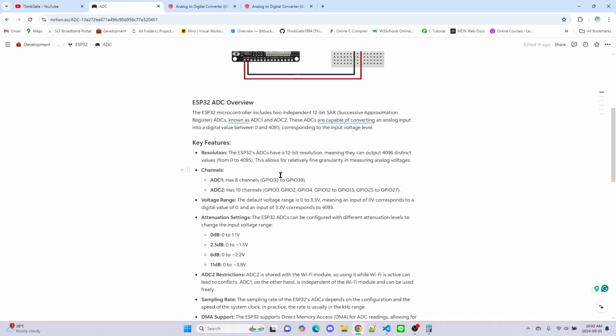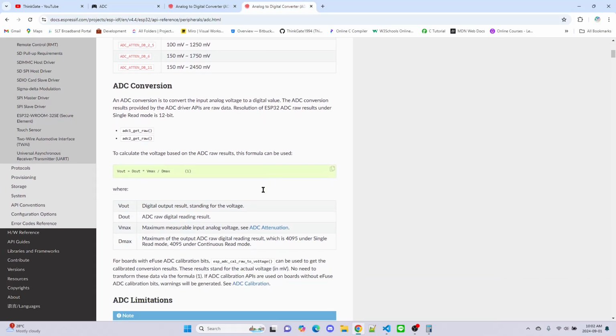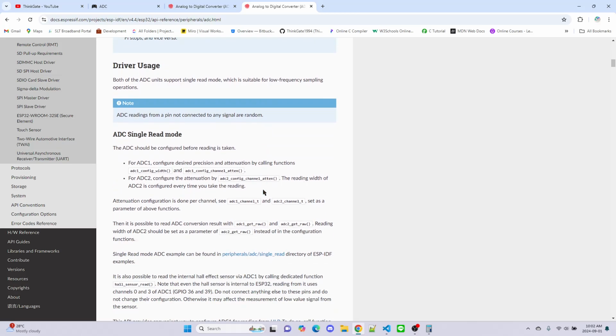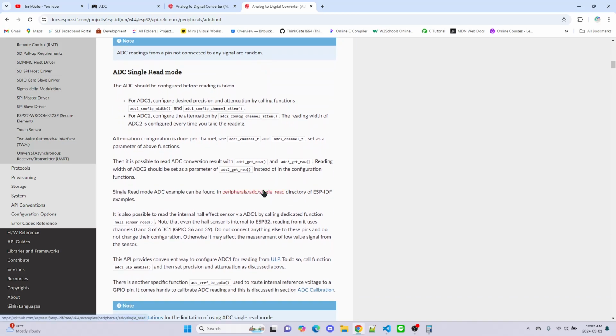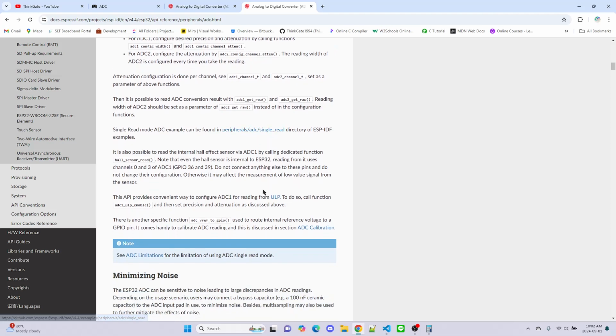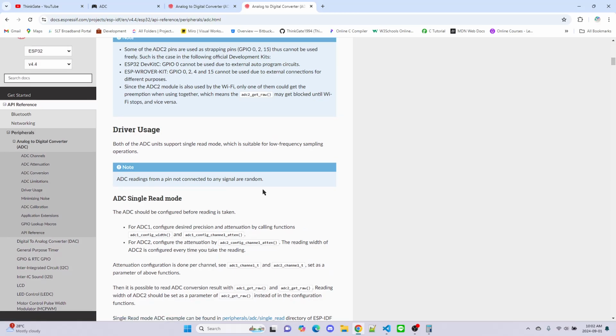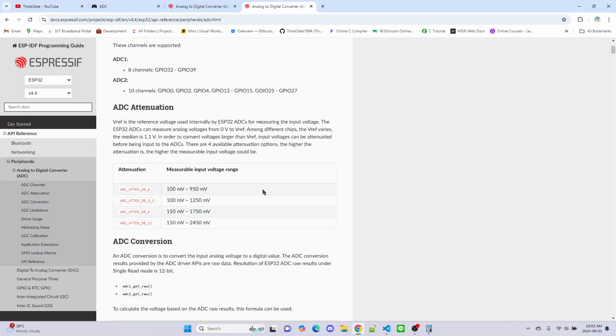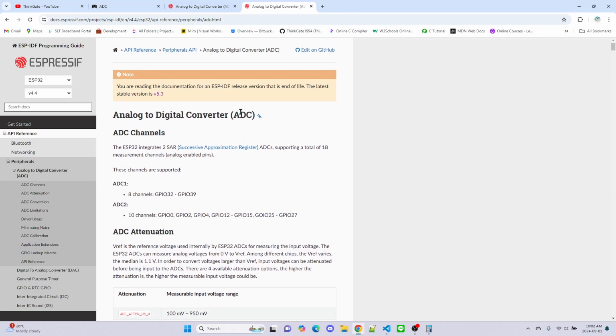If you are using Wi-Fi and GPIO analog input in your project, make sure the IC model that you are using is not using one of these GPIO inputs. This information is mentioned in this document, and I highly encourage you to go through it before getting started on programming the ADC.